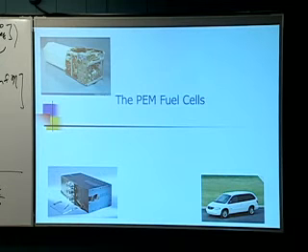Well, in this case, the fuel tank on this car, boy, I'm going to get all the way past my introductory slide, which says the title on it. The fuel tank in this car is sitting right back here where the regular gasoline tank sits. It takes up no more space than that does. And it's just a polyethylene container in this case because we're using sodium borohydride aqueous solution. So the density of that is essentially the density of water, a little more than the density of water. So it's very comparable to the gasoline that you're carrying around. It's a little heavier because of the density difference.